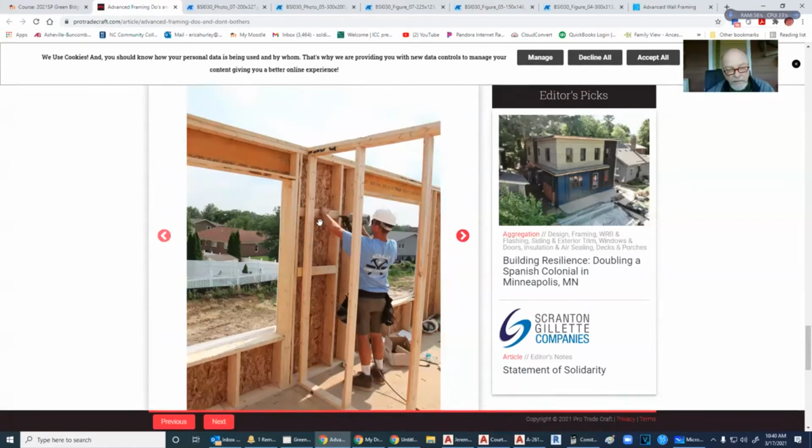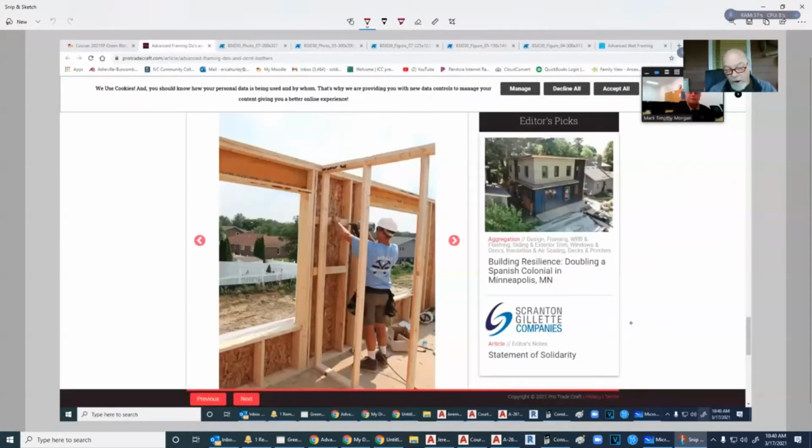And generally, different people do it different ways. The ladder would be cheaper, wouldn't it? Probably, because it's made out of 2x4 material, but it all depends on what this distance is. Are you going to need 1 or 2 studs? One 2x6 down through here, attached at the top and the bottom, might be cheaper. As a general rule, I always put 1 at the top, 1 at the center, and 1 at the bottom, and it was a done deal. I'm assuming he's going to put 1 here, and that way he can toenail into the plate here and into the plate here to have that connected.